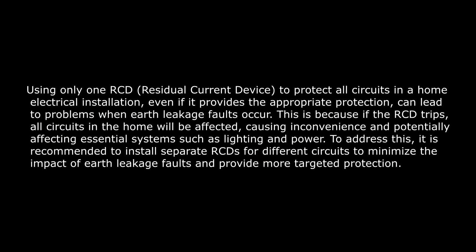Using only one RCD, residual current device, to protect all circuits in a home electrical installation, even if it provides the appropriate protection, can lead to problems when earth leakage faults occur. This is because if the RCD trips, all circuits in the home will be affected, causing inconvenience and potentially affecting essential systems such as lighting and power. To address this, it is recommended to install separate RCDs for different circuits to minimize the impact of earth leakage fault and provide more targeted protection.